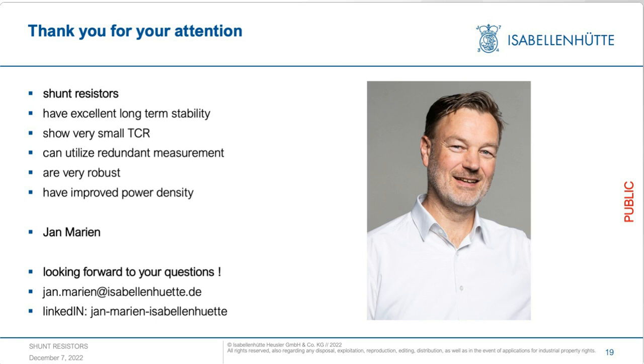However, with such a temperature measurement, there's always an error associated, and there's also a time delay associated. So when you use temperature sensors like NTCs or any other temperature sensor, you typically have a delay of some seconds, and you also have an error, and all this contributes to the overall accuracy of the measurement.